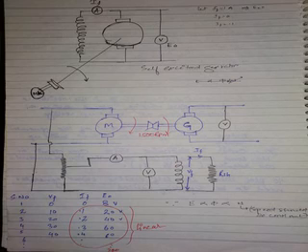Now, the test is very simple. You have to apply slowly from 0 to the maximum rated values of voltage as well as current, slowly. So first start the motor, run the motor at the rated speed of the generator. Let it be rated speed, which is maintained constant. Then let us make V0 and I0, let us make VF and IF also 0. No field winding, let us imagine like this.